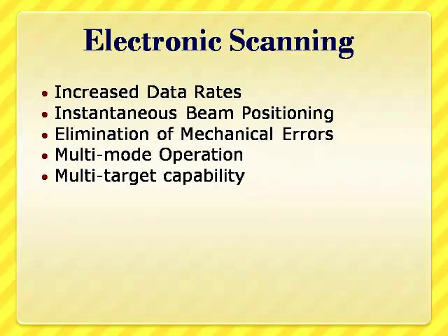That means multiple beams can be produced by the same antenna array and they can be used for different applications. Ideally, if you are going to have n number of elements in this antenna array, you can generate n multiple beams for different types of jobs.